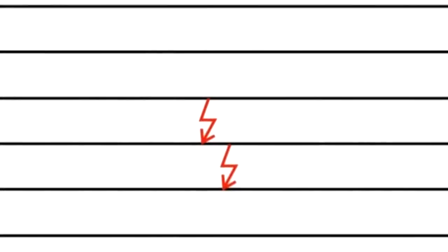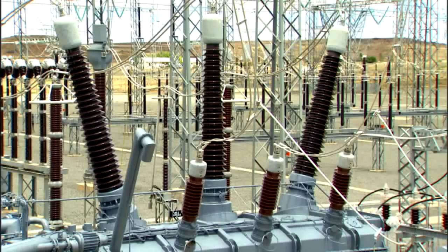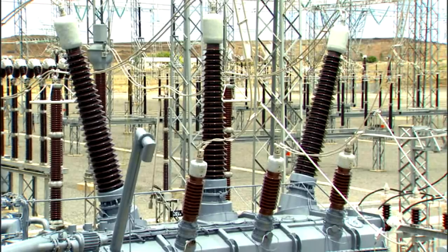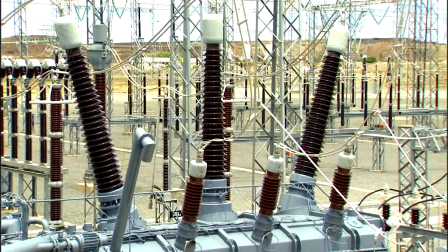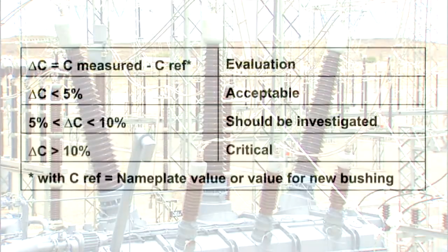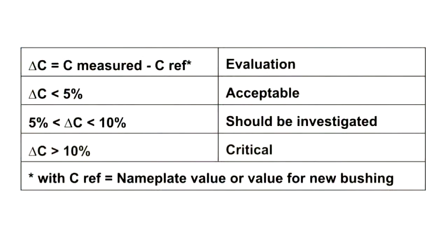Capacitance values of bushings show whether there have been partial breakdowns between control layers. For resin-bonded paper bushings, cracks into which oil has leaked can also change the value of the capacitance. A rise in capacitance of more than 10% is normally considered to be dangerous, since it indicates that the insulation distance is no longer sufficient.